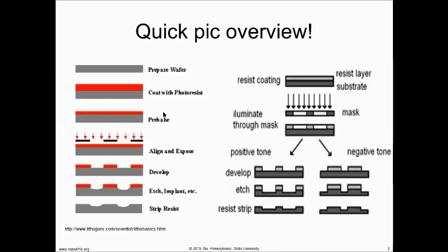The resist is on there, but the resist is wet, and it's an organic polymer, so I always describe it by analogy. It's kind of like a tar and kind of like nail polish, kind of like that stuff, but it's photoactive, right? But just something that you would know as a reference. So if we would put my mask right on top at that point, it would stick. Does everybody see that? So it's like wet nail polish. So what we're going to do is what we call pre-bake, and that's going to dry the wafer out.